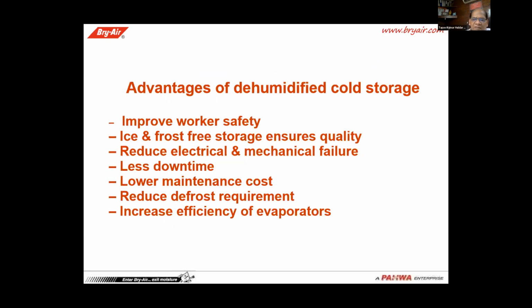in the evaporator coil. Less downtime, as otherwise we have to defrost. If the defrosting cycle is high, then definitely the downtime will be higher. Lower maintenance cost, of course, if you are controlling humidity in the room, then maintenance cost will be very low. Reduced defrosting equipment. Of course, if you maintain humidity inside the cold storage, then your defrosting equipment itself is going to be reduced. Increased efficiency of the evaporator.